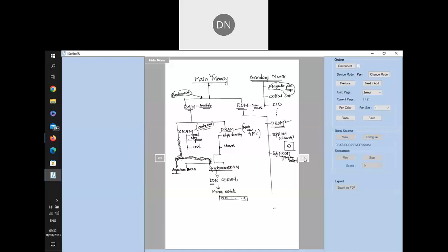So after this, very recently, instead of E-square PROMs, flash memories are available now. Flash memory is nothing but a memory where you don't require a separate programming voltage. The flash memory chips are used in your pen drives and your SD cards, which you can read and write without a programming voltage.